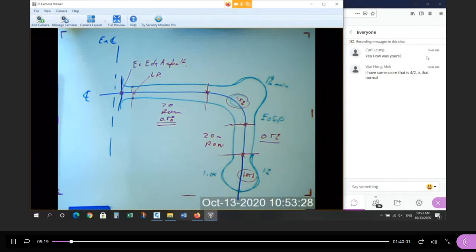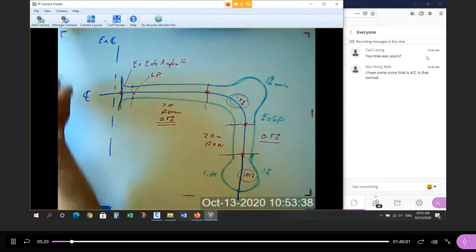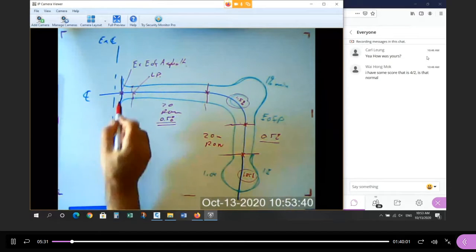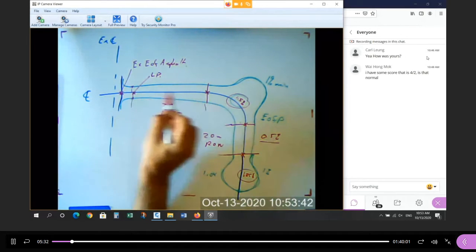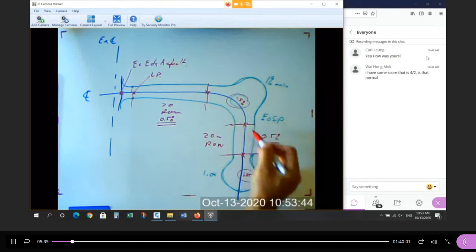Sometimes 1%. This is Town of Richmond Hill standard. Next semester, I believe the standard is 0.75%, always steeper than the minimum half. So based on that, we go to our profile. On our profile, in the plan view, we put points in the plan at these special locations. Right? So I identify the station values.